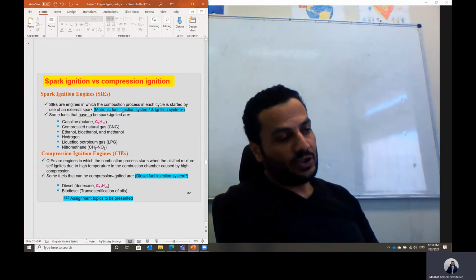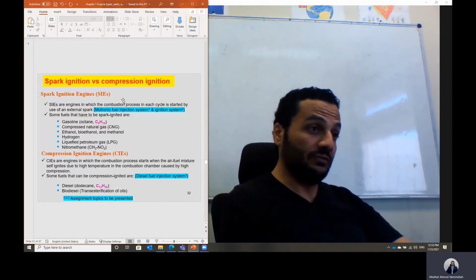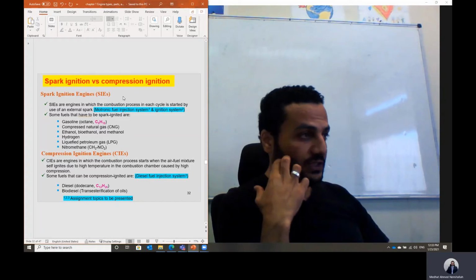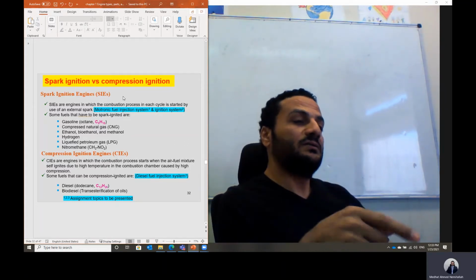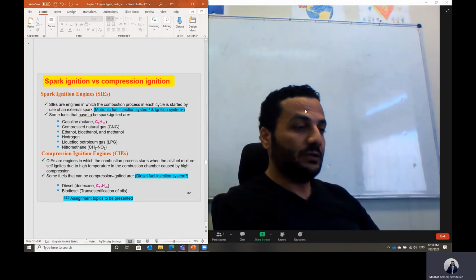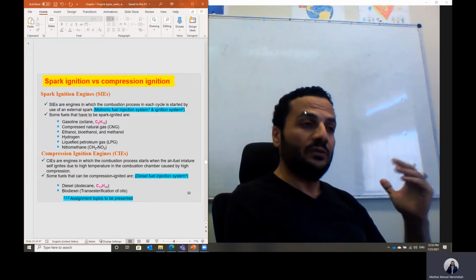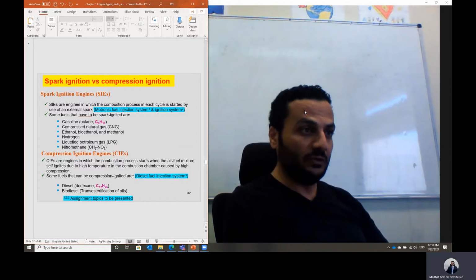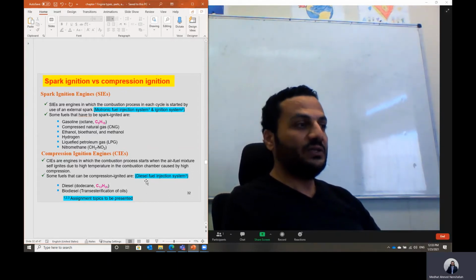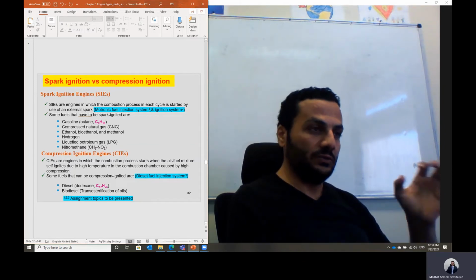In gasoline engine, we control the amount of air through the control of the throttle valve opening, which is connected to the accelerator lever. So we control the amount of air. And in this case, the fuel is calculated by the electronic control unit, based on the required load, the throttle valve opening, and also the required engine speed, we can decide the amount of fuel to be injected.